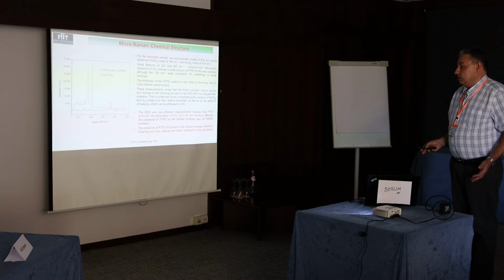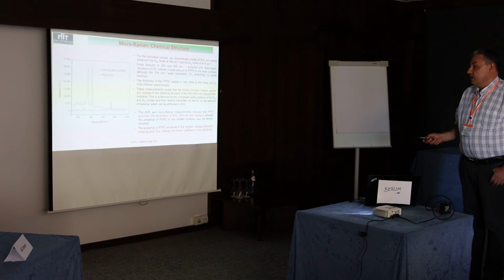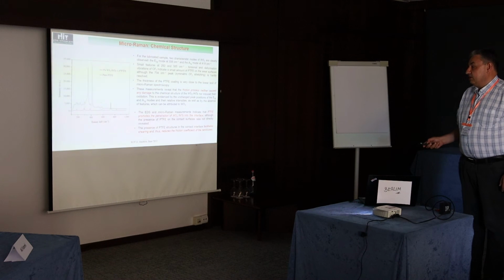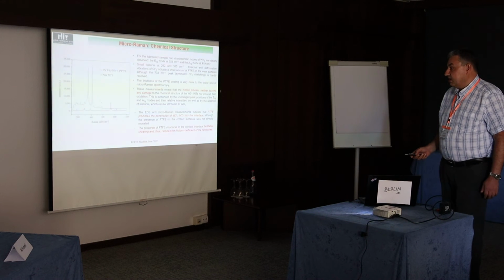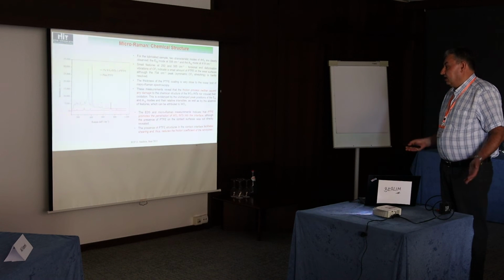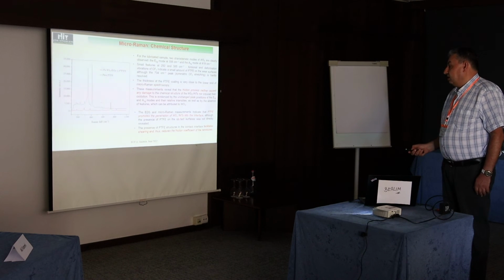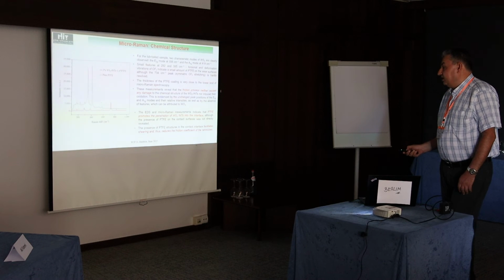But what's more important is not that we see this Raman peak, but what we don't see. We don't see any change in the relative intensity of these WS2 peaks, which means that there is no damage to nanotubes. There is no formation of oxides generally observed in this area. I mean tungsten oxide, which is a very frequent process in the case of friction and temperature treatment and damage and so on. So the EDS and micro-Raman indicate that Teflon promotes penetration of WS2 nanotubes into the interface,